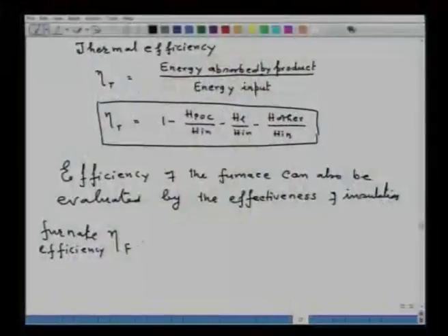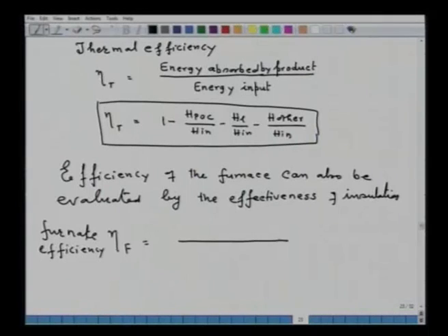So, that is equal to energy in minus heat loss. Remember, when I say heat loss, that means the loss through the lining of the furnace. The heat taken by POC is not considered to be loss, because it is an inherent feature of the energy achieved by combustion of fuel.